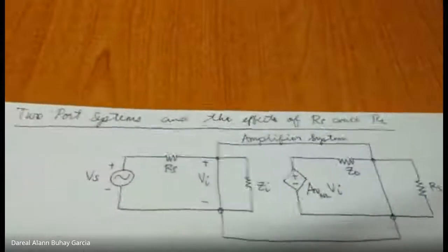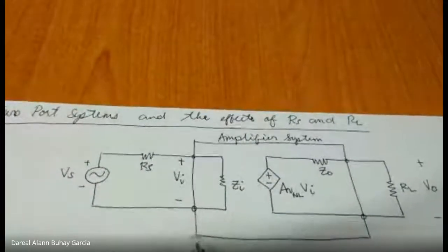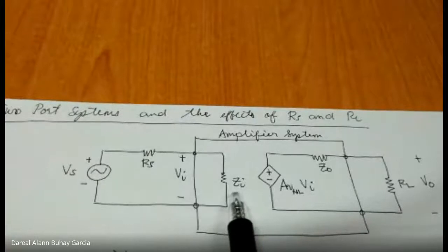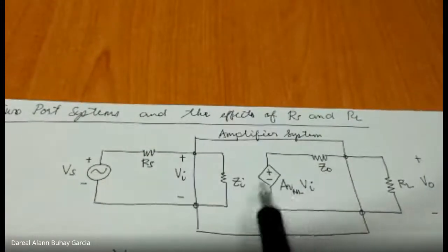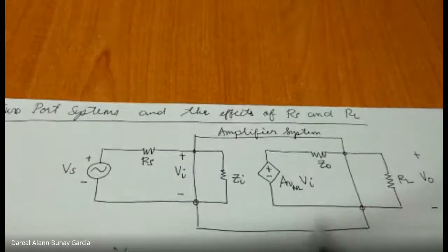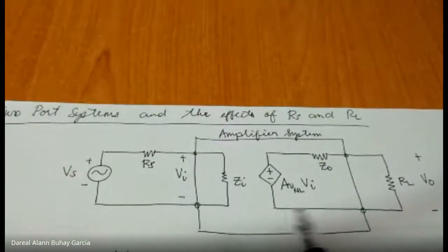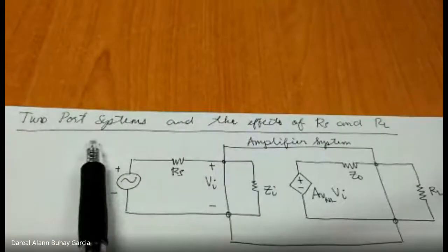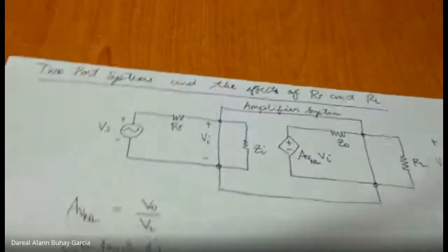Now, a quick review of cascaded circuits and two-port networks. For two-port analysis, we only need those three parameters: input impedance, output impedance, and voltage gain. Fortunately for us, the analysis of a two-port system, whether BJT or FET, is the same. So the formulas apply equally. Okay?